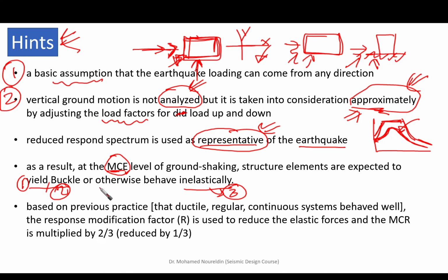Because we are expecting hysteretic energy dissipation by yielding and buckling and so on, and this is represented through the reduction of the response spectrum.